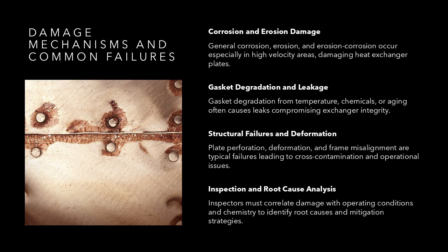This slide consolidates typical damage mechanisms and failure modes observed in plate heat exchangers, as described in API 572 and industry experience. Common mechanisms include general corrosion, erosion or erosion corrosion in high-velocity zones, pitting and crevice corrosion under gaskets, and stress corrosion cracking depending on material and service.